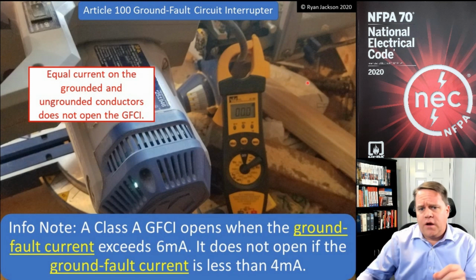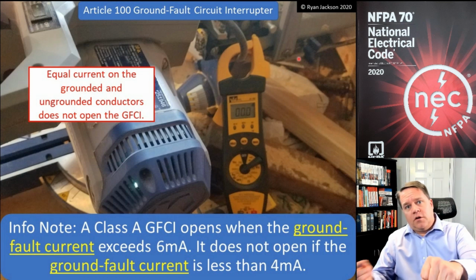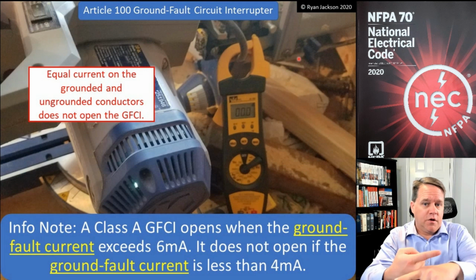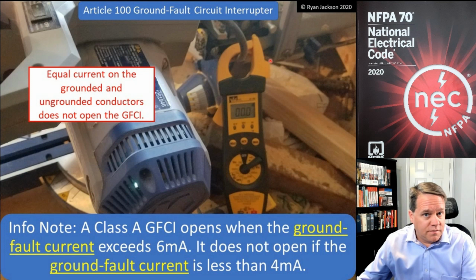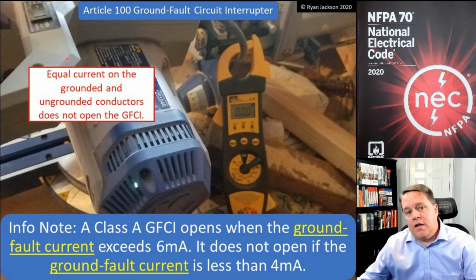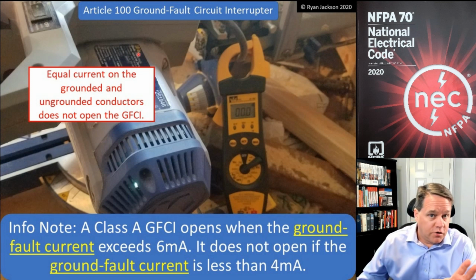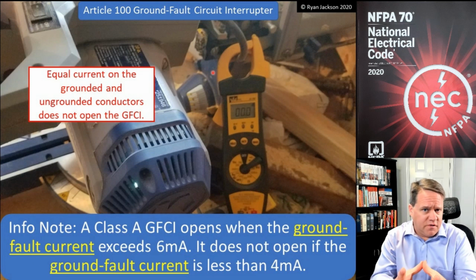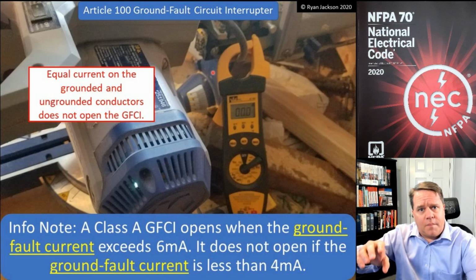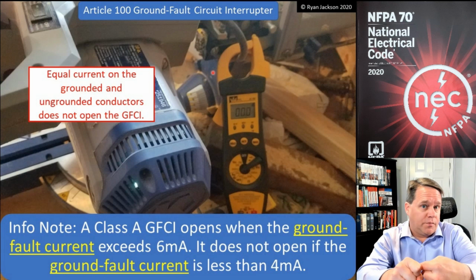So what I'm showing here is I have clamped my ammeter around this 2-wire cord. I pull the trigger, 10 amps goes out on the hot, 10 amps comes back on the neutral, so it results in a net zero effect if I'm measuring the current across both. If I had a ground fault, let's say inside this saw, a frayed cord or something on the internal components, so the cord energizes the metal parts of the saw, and I put my hand on my metal table and pull the trigger and I get shocked. Well, the motor itself still pulls 10 amps.